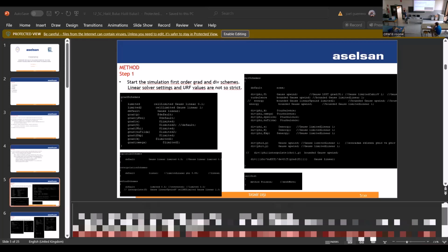To add the contribution of the density correction, the transonic switch must be turned on. In that way, you're gonna add the density correction terms to your linear equations. But if you have a low Mach number problem, there are no actual density oscillations.